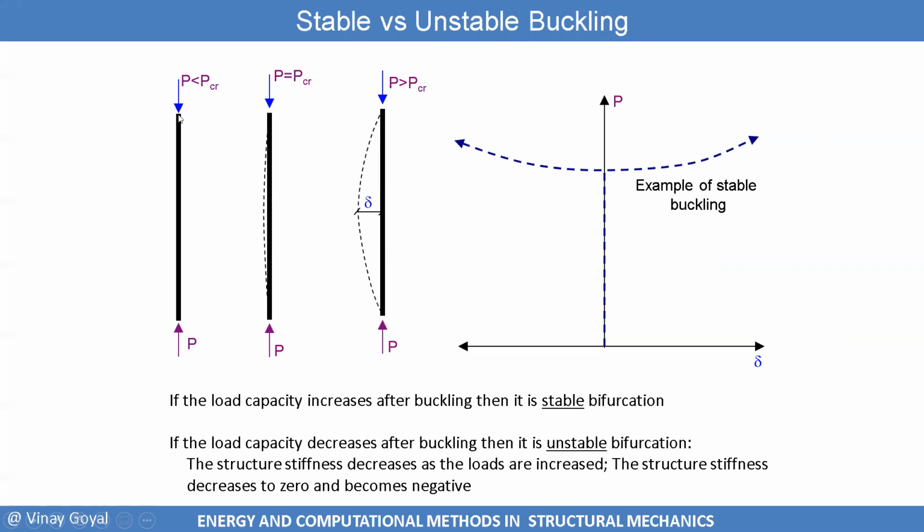What does buckling mean? We already talked about loss of stiffness. It could lead either to excessive deformation or not so much. When you remove the loads, maybe it returns. But if you take a ruler at home and apply an axial load in compression, that ruler should bend quite a bit quickly. The critical load for a ruler tends to be very small. But the bottom line is that if you apply a small amount of axial compression to the ruler, it will stay straight. There's no deformation that will occur out of plane.